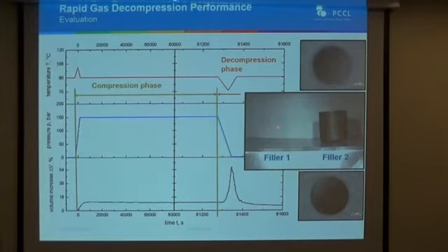On the left side, we have spontaneous crack initiation, and the crack grows until the surface of the material, and therefore the high pressure gas in the middle of the material can rapidly or explosively go outside of the material, and therefore the material is blown away outside of this camera window. Afterwards, we also cut the specimens, and we see for the first material the crack going out through the complete cross-section of the material, and here we have no crack observed with the second filler.